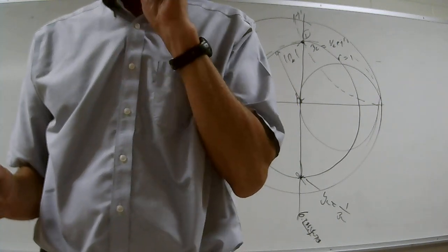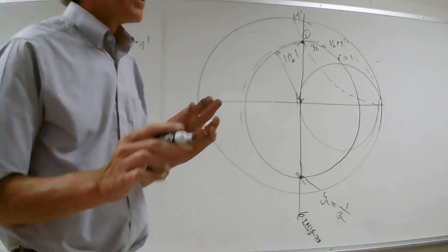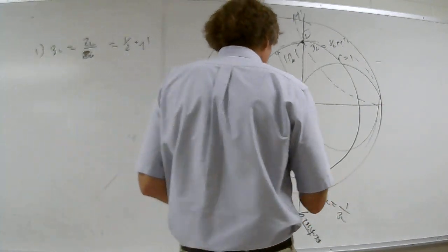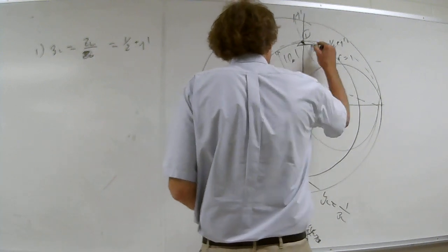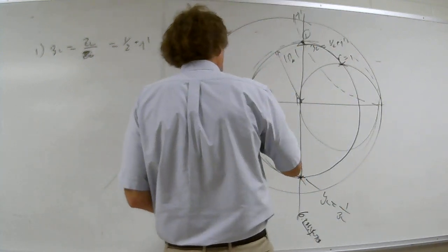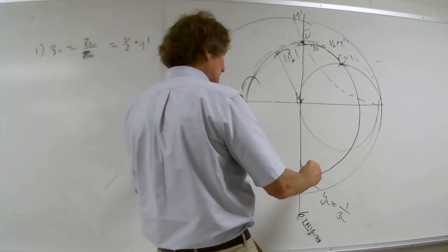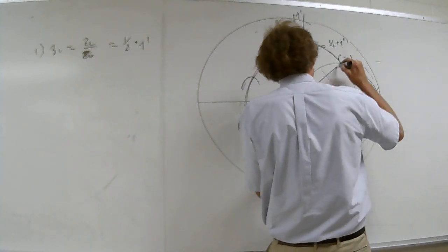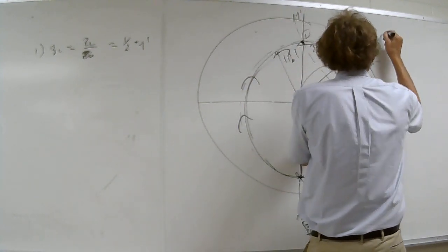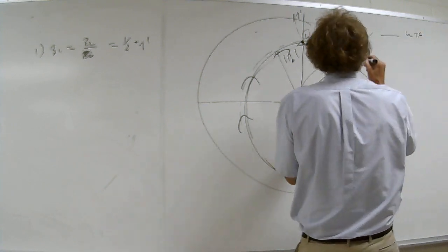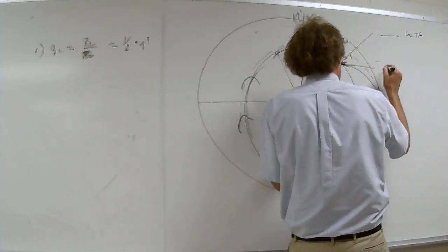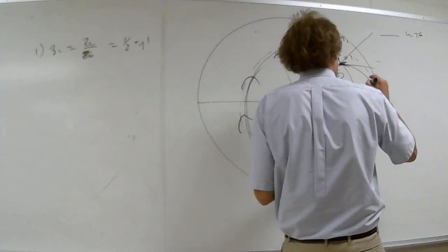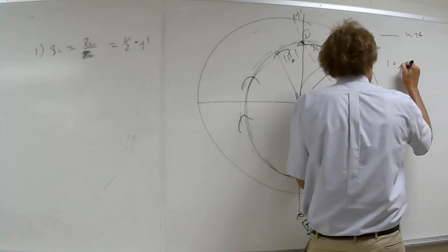We're going to move from there, and I want you to hear me now. Just like we did before, but remember, we are in the admittance domain. Got me? And we're going to move from there until we hit here, the 1 circle. So we're going to move all the way around. That was our normalized load admittance until I hit here. And then draw a line right through there, as we've done before, and give me the wavelengths towards generator. And remember, this point, I'll call this, that was 0.1, this is 0.2. Call this 0.3. And this is going to be 1 plus J something.